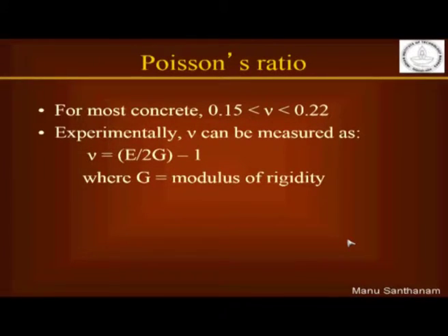Poisson's ratio, once again, can be measured in the same experiment as your modulus of elasticity. Again, you need to affix strain gauges in lateral and axial directions. Please remember, when you talk about lateral in the case of a cylinder, we are looking at circumferential change. So you have to use the right kind of equipment, right kind of monitoring to determine these values, and obviously you can calculate your Poisson's ratio as the ratio of the lateral strain to the axial strain.